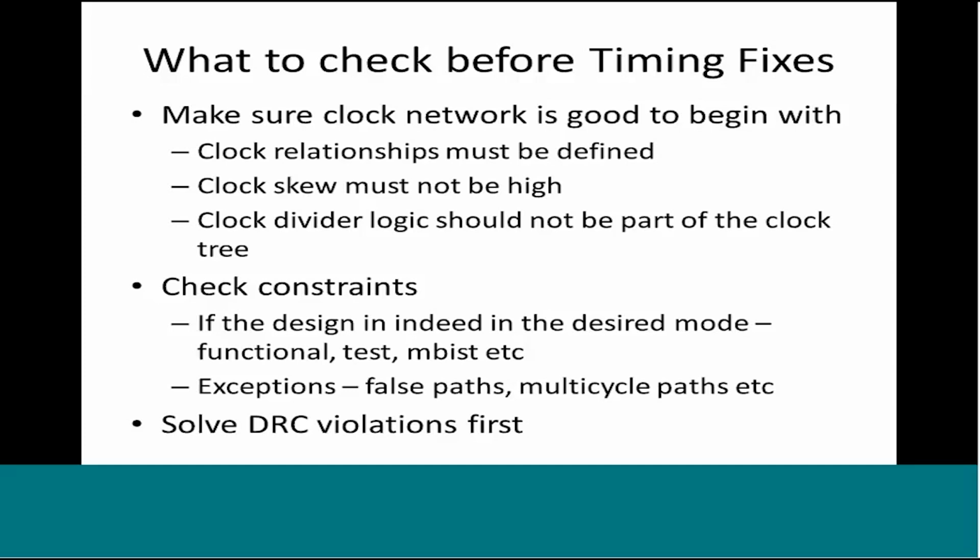Now, after the routing is done, after you get the parasitic database, any backend tool will try and fix most of the violations. But even after the first round of it, you will be left with a few hundred or even a few thousand violations. And now there are tools. People have written sets of scripts.